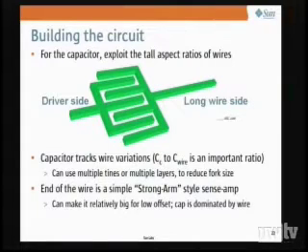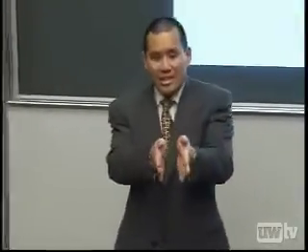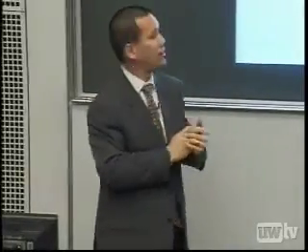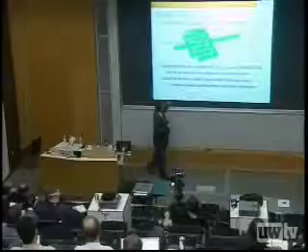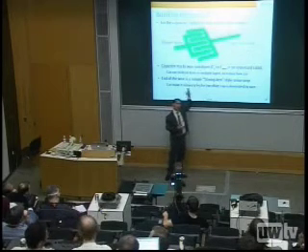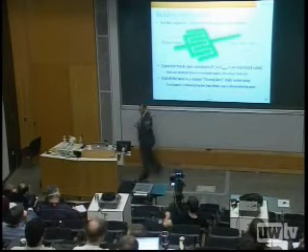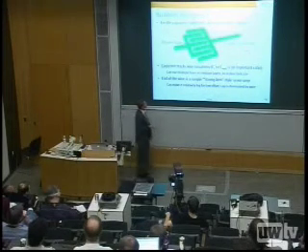How do you make this circuit? Well, you need a capacitor. And one thing we did when we did this chip is to look at, well, what's a good linear capacitor that doesn't care about voltage bias? Well, you look at wires. A wire's capacitance is mostly side to side, no longer top to bottom, right? So I can make a capacitor out of interdigitated wires in a pitchfork scheme. Now, this is interesting because what I really care about is a ratio of this coupling capacitance to the wire capacitance. And this will track variations in wire capacitance. If I didn't care about that tracking so much, I could use multiple metal layers, of course.